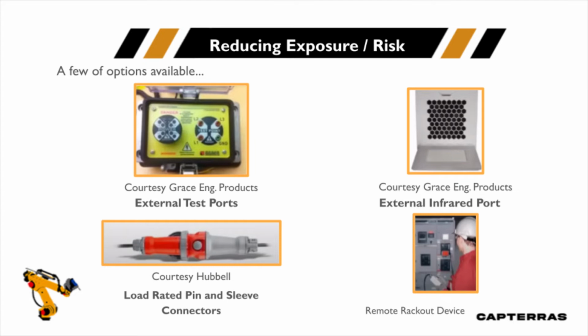So here are some examples of reducing exposure and risk. On the left, we see an external test port. This is an actual voltage test port from Grace Engineered Products, here on the safe side. On the right side of this device, you can see where you can actually plug in test leads. So we can put this external to a piece of equipment. If we're doing lockout, tagout, let's say, we can shut off the device and test it without ever having to PPE up.